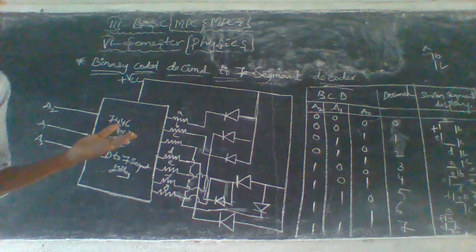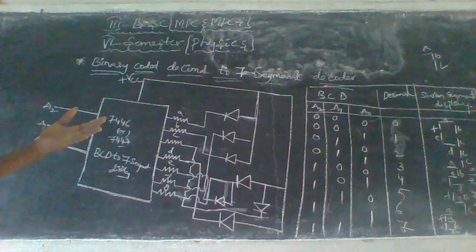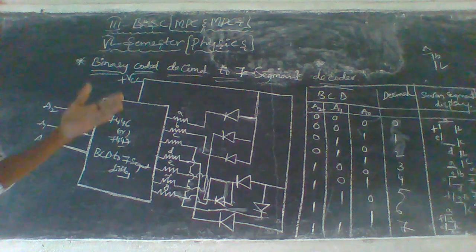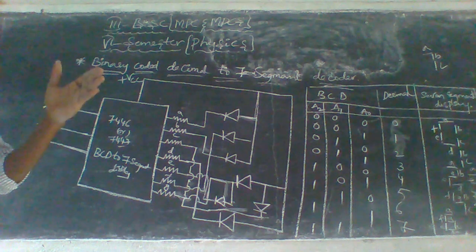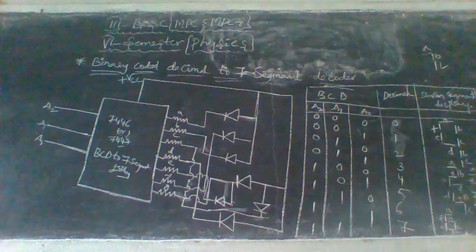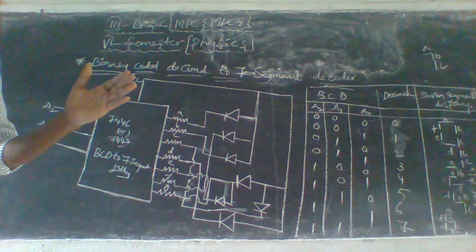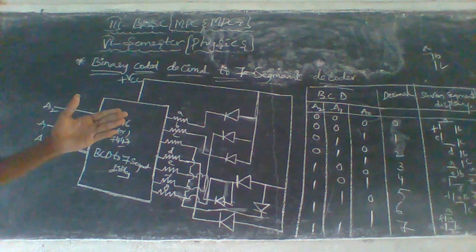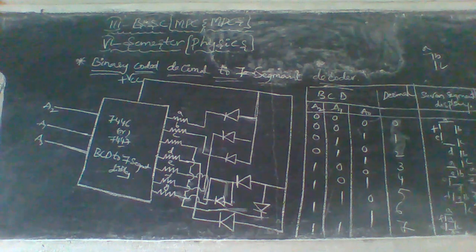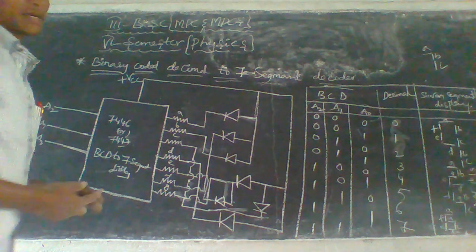Because in the truth table the first combination corresponds to 0 and the last combination corresponds to 9. Similarly, the rest correspond from 1 to 8 from top to bottom. Okay, so here BCD numbers only range from 0 to 9. Thus the inputs from 10 to 15 are invalid inputs. Okay, so now we can see the Boolean expression of BCD to 7 segment display truth table.